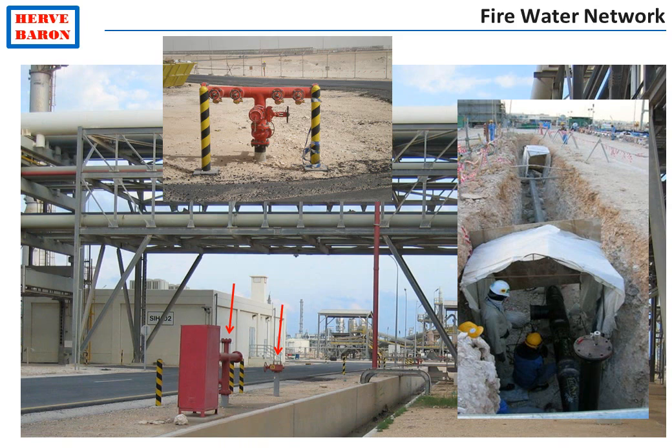The fire-water network entails a looped fire-water distribution ring, together with numerous isolation valves, hydrants which have to be accessible from the road. As you see, we have seen that there is a number of systems: the rainwater collection systems, the process drain systems, the underground cable systems, the fire-water systems. All these systems have to be coordinated by the civil engineer.